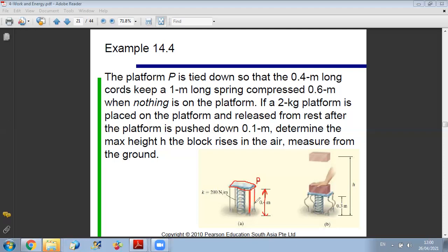These rigid links can be compressed, okay, but cannot be stretched more than 0.4. As you can see here, when you compress, they will deform. But when they will be straight, their maximum distance from the ground is 0.4, since they cannot be stretched. Okay? So this is why they will force my plate to be at a maximum distance of 0.4 meters